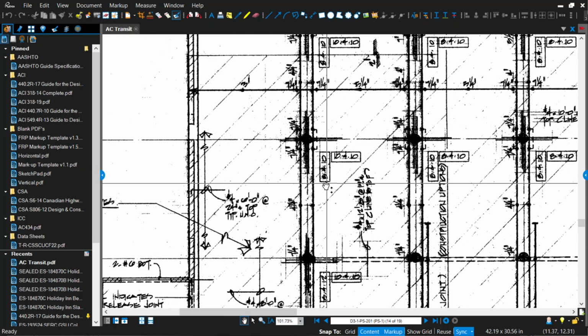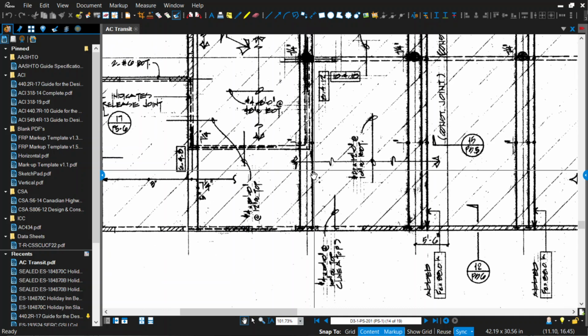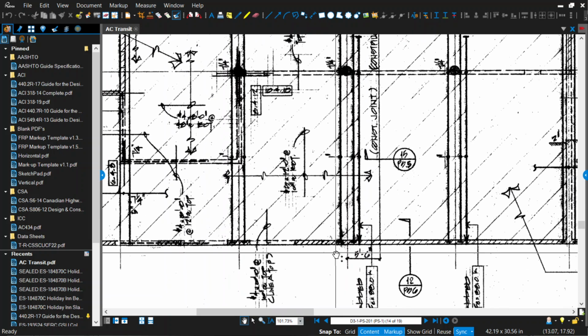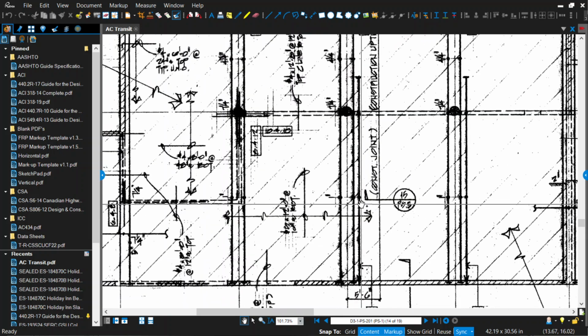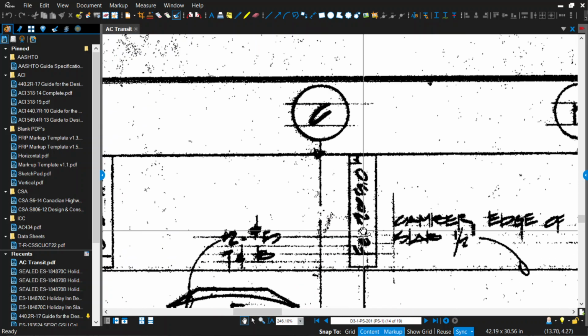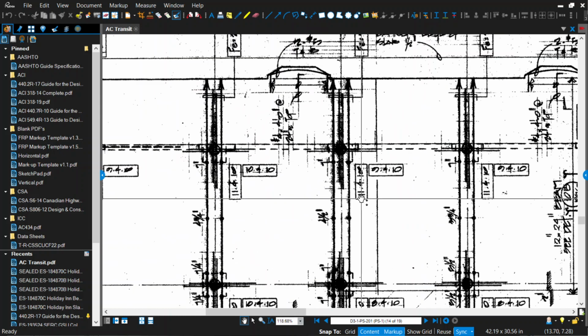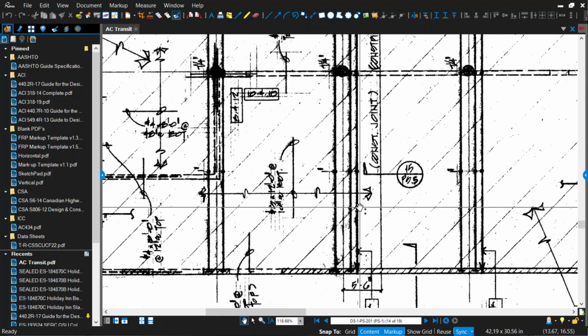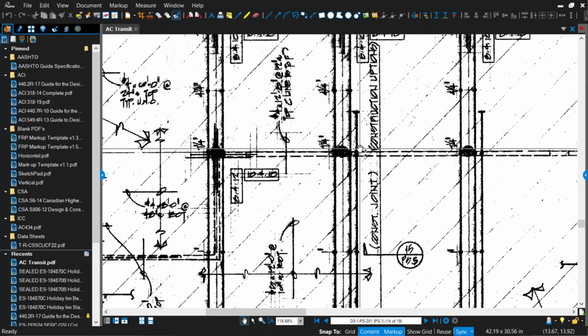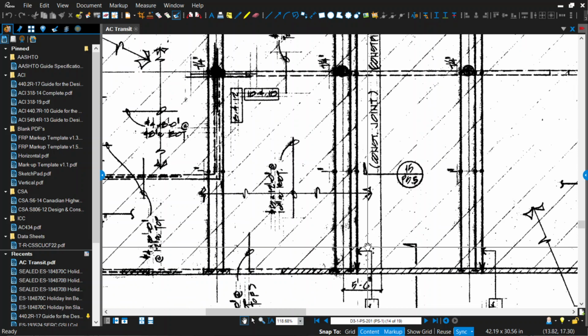And that group is the whole entire way. For that one, there's no added cables, but for this one, it's 38, let's say, plus whatever this is. So you have to add the 2 numbers together for the entire force in that last bay or span. So the only reason this added cable goes back this far is because it has to get down from the high point to the midpoint of the slab. So that way you get the full profile that you can get for that bay.